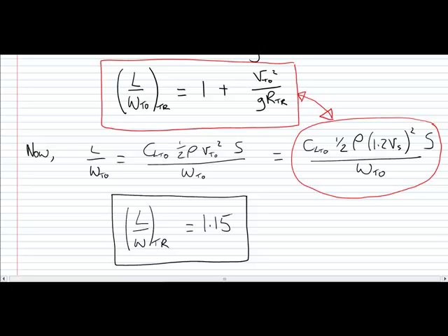So if we equate this expression here with our definition for the load factor during this phase in terms of lift coefficient, then we end up with this expression for the load factor, or the lift relative to the weight, that's required through the transition phase.